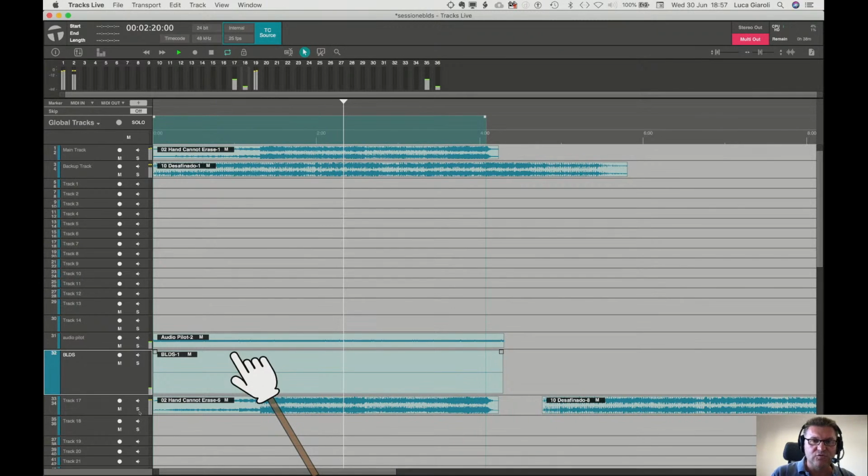For a live show and not a playback show, remember that in the Prodigy series, both the MP and the MC, in the generator, you have the BLDS generated in real time. So you can route it towards the output among MADI feeds or Dante or whatever. In that case, you don't even have to play it back, but the BLDS can be generated in real time from the Prodigy series.